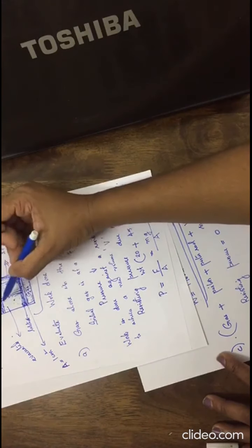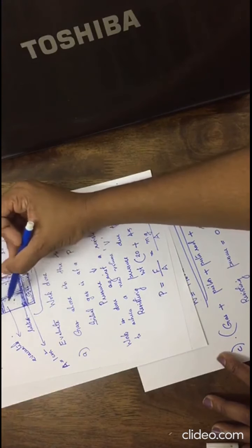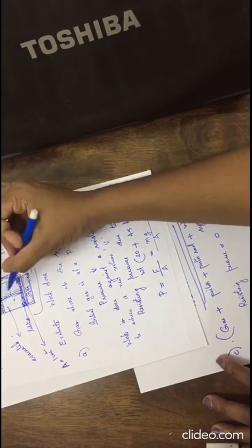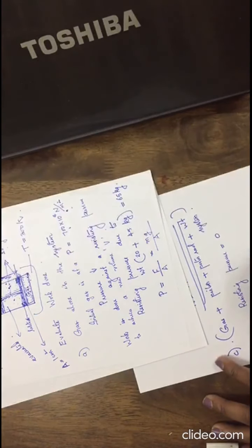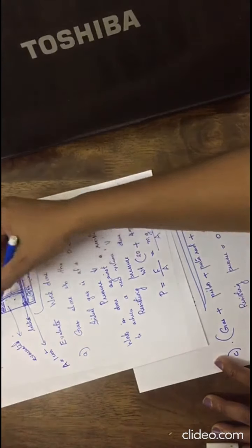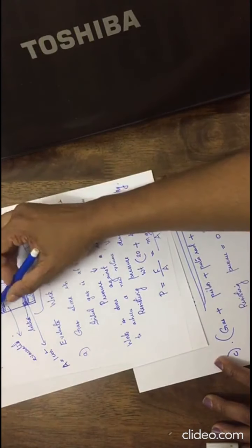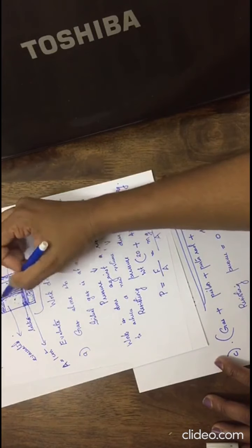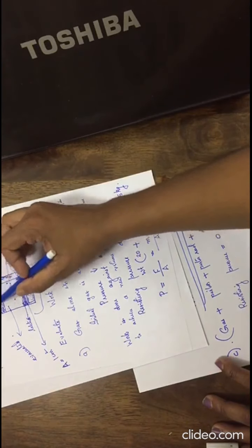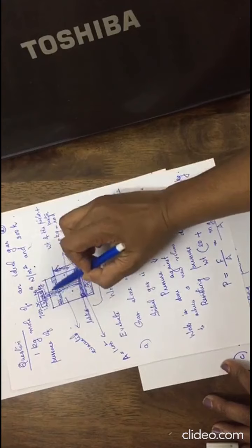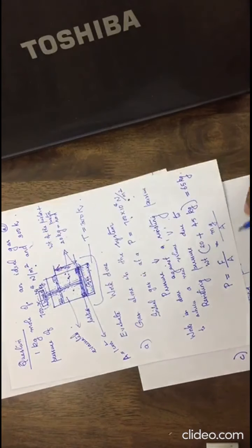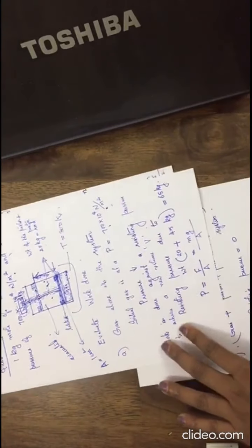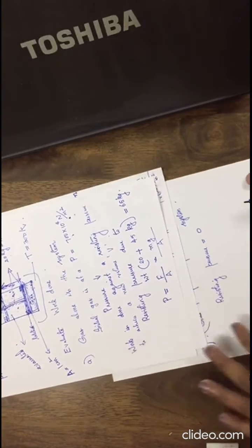If air is there, then you can assume atmospheric pressure exerting as the external pressure. So the resisting pressure now is 0 because it is devoid of air, and at the same time we consider the entire piston cylinder assembly plus the additional weight kept on top as the system.